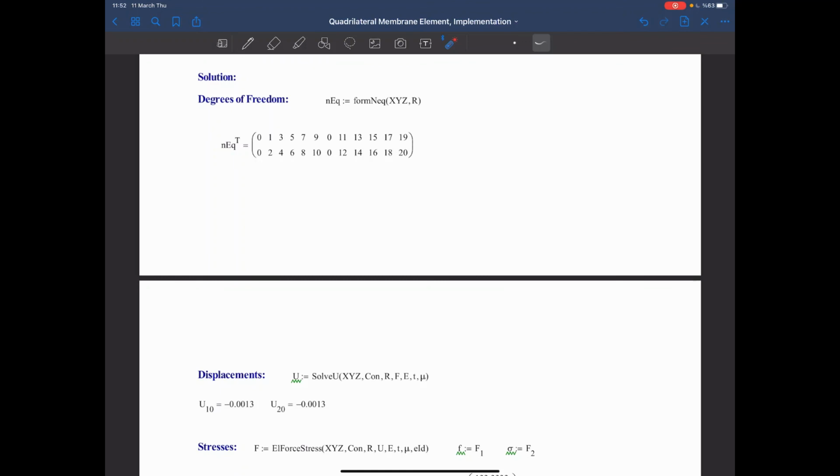Now, when you use a coarse mesh, you get very stiff results. As you increase the number of elements, the behavior becomes more flexible. So you go from stiff behavior to flexible behavior and converge to the analytical result. After a while, you will not see a significant difference, and that's the point where you should stop. You don't need further elements.